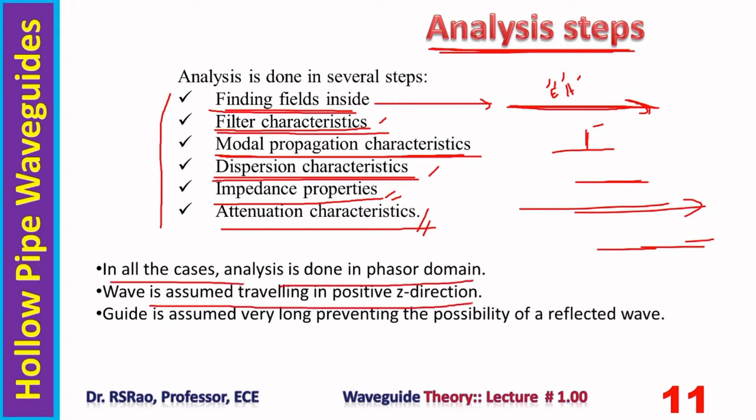Wave is assumed to be traveling in positive z direction. Guide is assumed to be very long, preventing possibility of reflected wave. So, in the analysis, we do the analysis in phasor domain and we assume only a single wave is traveling, no reflected wave or no standing waves.